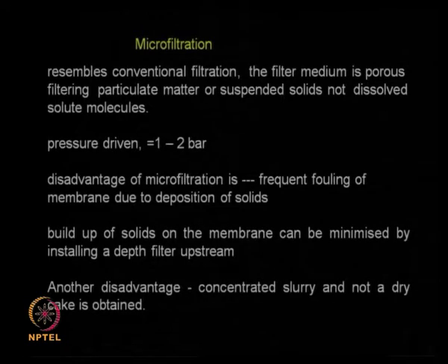You have hydrophilic membranes, you have hydrophobic membranes. It is used for separating practically a large number of varied components. We did talk about microfiltration some time back. Let me again recap on that. It resembles a conventional filtration. There are small pores in the membrane material. So the solids which are very small will go through the pores and the remaining solids will get filtered out. So it is almost like a normal filtration process.